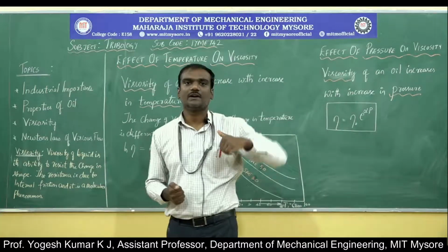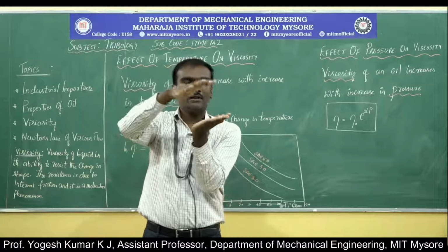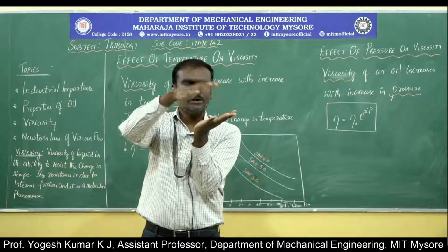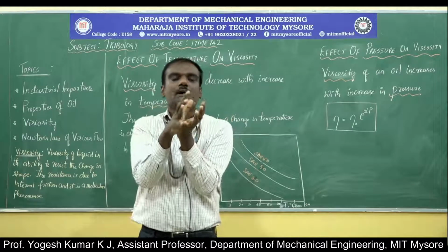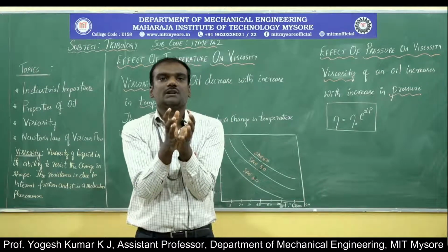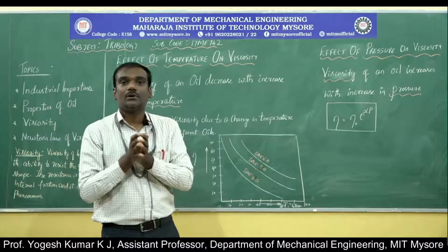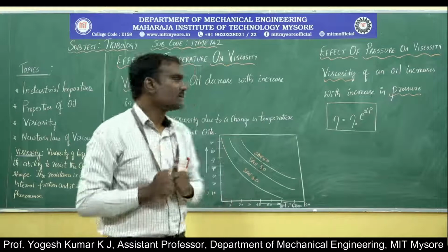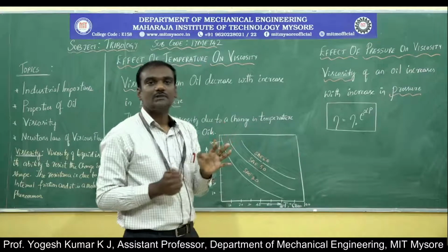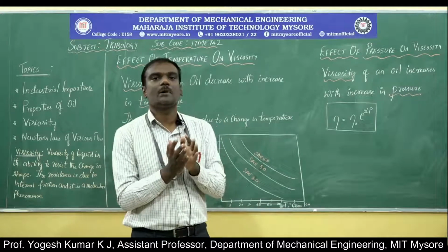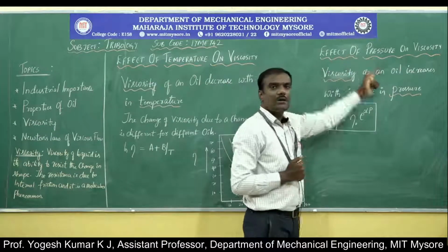As the pressure increases, the bonding between the lubricating molecules present in the oil is strengthened, the molecules come closer to each other, and the fluid becomes more thickened. So as the pressure increases, the viscosity of an oil increases, because the intermolecular forces between the molecules are increased.